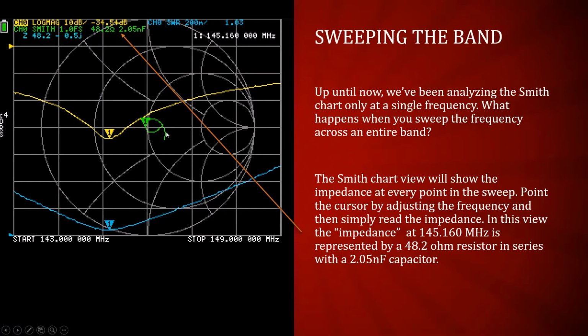And you can also see the reflection coefficient. But the reason that Smith chart view may not be reasonable to you or useful to you is because your VNA calculates all of this stuff anyway. You want to know what the input impedance of this thing is going to be. You put your cursor down here, and all right, here's log mag 10. This is return loss. All right, that's what they call return loss for some reason. It would be nice if they called it return loss, but log mag is 10 dB per division, and you can calculate it. Here's your reference point, this little thing over here, and you can see 1, 2, 3, maybe 3.5, something like that at the cursor point.